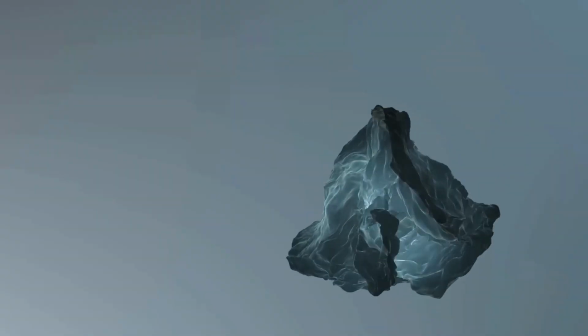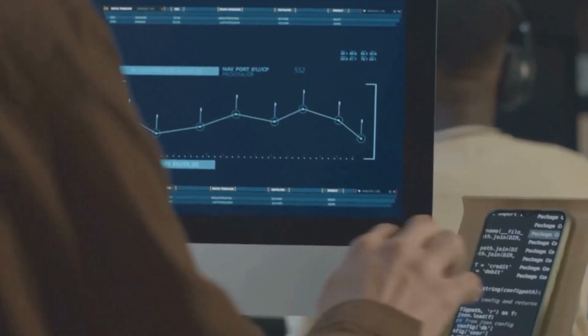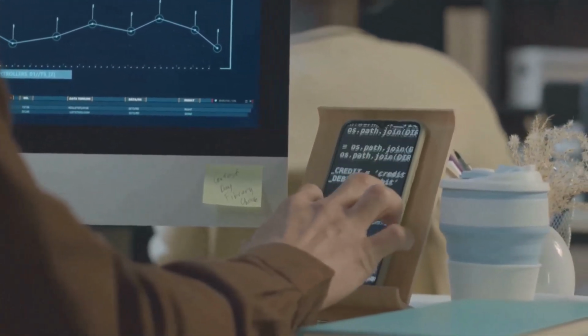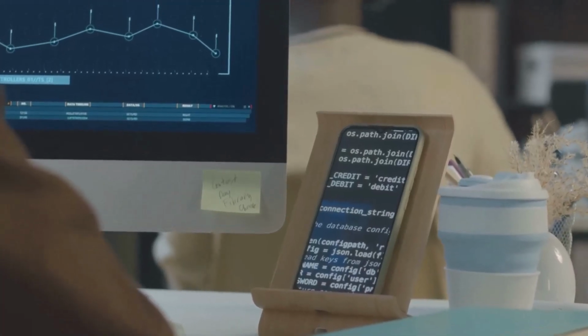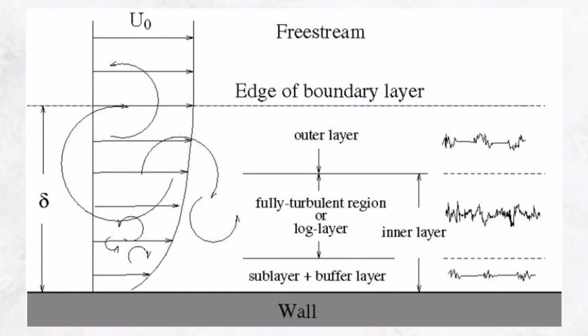This special ruler helps us understand which part of the boundary layer we are in. Close to the wall, where the fluid is slow and sticky, the Y+ values are small. As you move further away from the wall and into the faster-moving fluid, the Y+ values get bigger. It's like a secret code that tells computational fluid dynamics, or CFD, software, such as ANSYS, exactly where it is inside this critical region. Getting this right is the first step to creating a simulation that actually matches what happens in the real world, which is what engineering is all about.